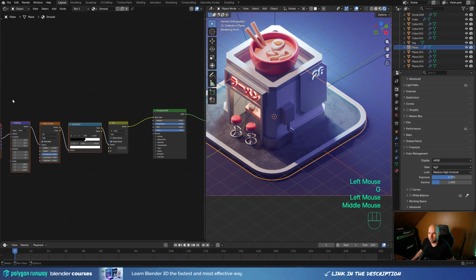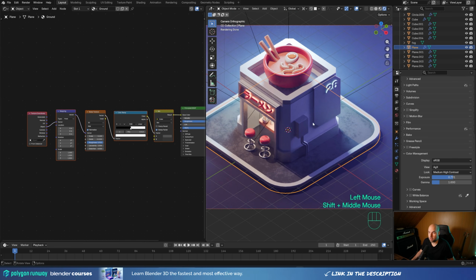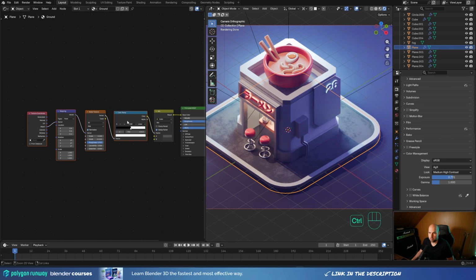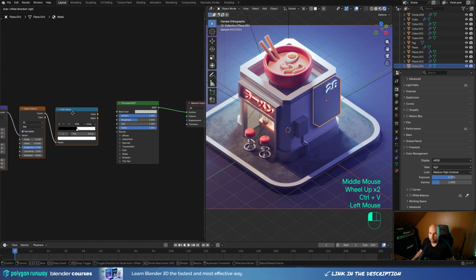So this is very simple, you know, grungy setup that will make your materials more sophisticated, and you can then use and plug this into different channels as well. So for example, the metallic material looks really flat here. So let me just grab this noise setup here, press Ctrl C, and let's select the metal material and press Ctrl V to plug this back in.